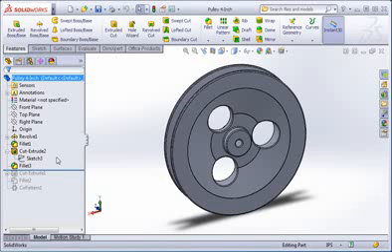Creating the pattern with the sketch pattern command took longer because we spent more time on the sketch, and we spent more time adding fillets to all the holes. Now we're going to change the number of holes from 3 to 4, and when we do you'll see why it's easier and quicker to use the 3D circular pattern command.